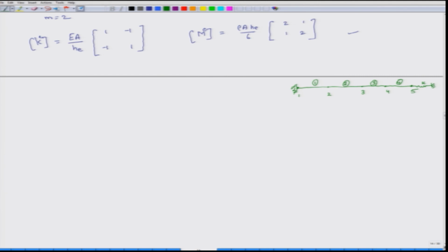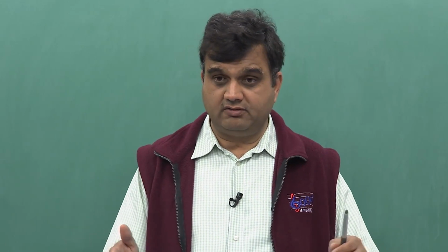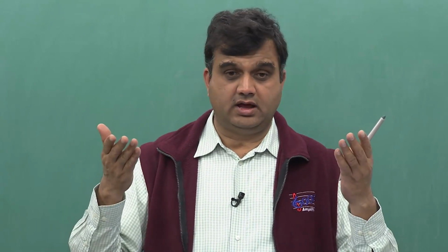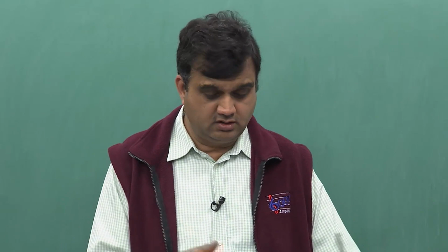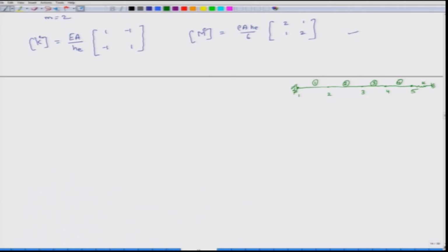Okay. One thing you will immediately note is that suppose this spring was not there, then the bar would have less problem vibrating back and forth, right. Once the spring is there, then the overall system becomes stiffer. So, the bar will have a higher angular frequency, because its overall stiffness goes up, right. So, we have to figure out how to incorporate the influence of this K in the overall assembly level equations, and to do that, first we have to develop the assembly level equations. So, let us write down these assembly level equations.